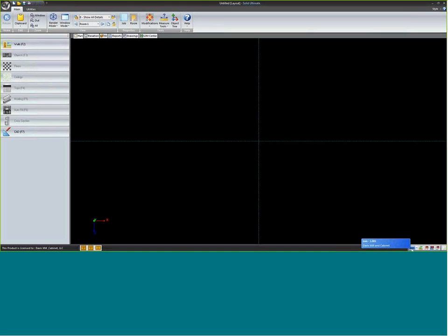If I click on the unit here, I can change the precision of that unit. I typically have mine set really accurately in millimeters. In inches, I typically go to 16ths. I know there are some people that like going to 32nds, and others that like everything rounded to 1/8 of an inch. So it's total user preference, and you can change on the fly between jobs. It's not anything universal. You'll have your system defaults, but you can change it whenever you want.